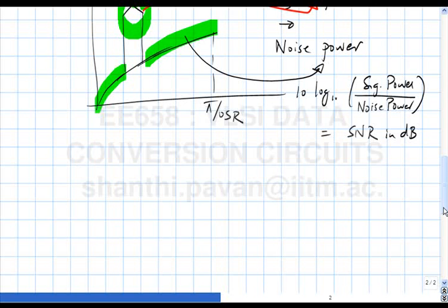Now, assuming that the model of additive quantization noise is valid, then depending on the record and the particular noise realization, you are likely to end up with different values of signal to quantization noise ratio. You understand? Because the input signal is fixed and clean, but this uniform random noise that is being added is stochastic. So if you take a small record, for some records the power might be small, for other records the power might be large.